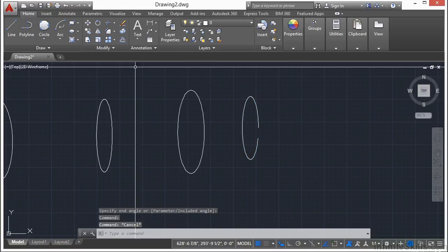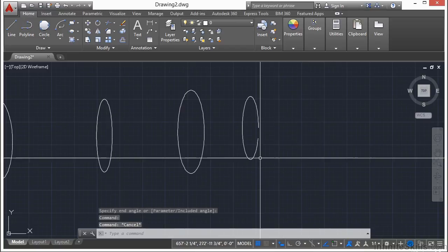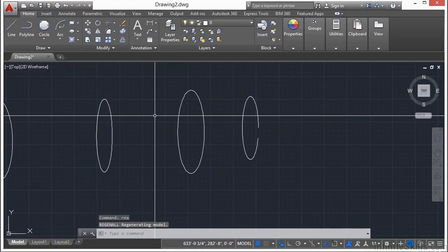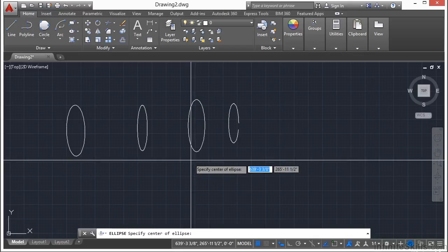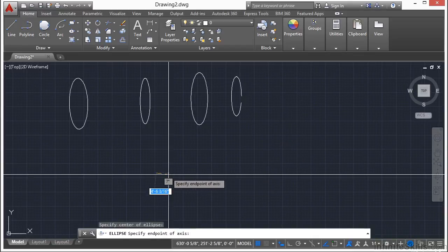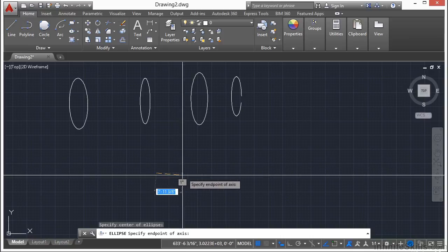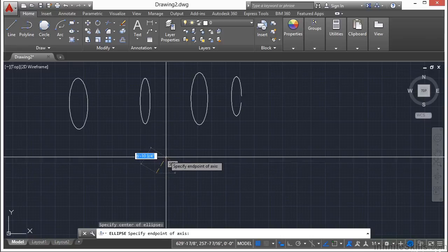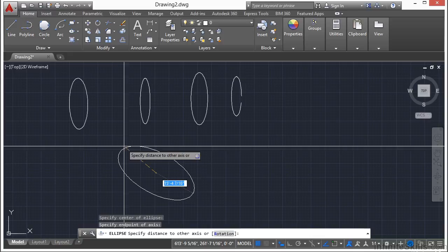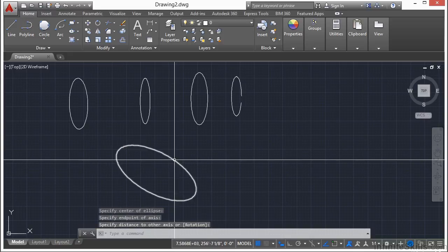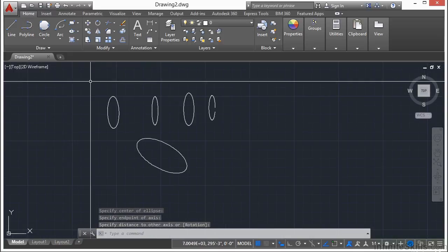Now the ellipse, keep in mind, if your ortho command is turned off, like I have mine off right now, when I pick my center point, and then I pick my width, it's going to be drawn at this angle. It's not perfectly horizontal or vertical. So it can be oblonged like that. So there are a lot of different ways to draw it. And it depends, again, on exactly what you're trying to draw, the perspective of it, or what information that you have at the time.